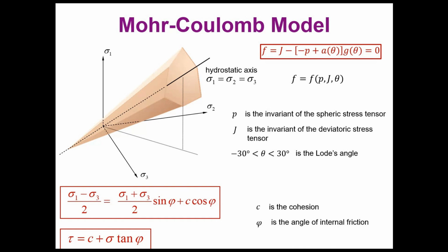So basically, you have two parameters to relate on clays, because clays have the cohesion as one of the main parameters to define the behavior, and you have the angle of internal friction for sand. So this means that even when this Mohr-Coulomb model is more for brittle materials, you have the possibility to study clays as well when they are present.